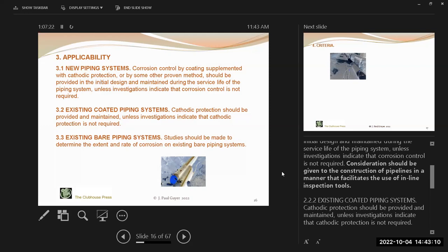And in this day and age, keep in mind, as far as the inspections of your buried pipeline, take advantage of the fact that there are now commercially available these pigs, which is a little propelled TV camera, basically, that will inspect the inside of pipelines and give you a more complete picture of how effective the cathodic protection and corrosion protection measures have been in preventing internal corrosion.